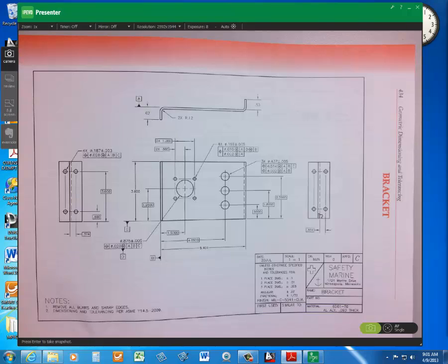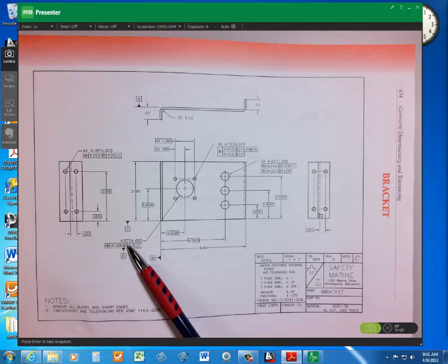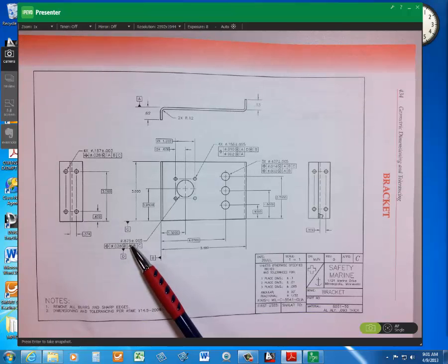All right. Now, the positional tolerances for the actual produced sizes. In reference to this dimension, when we produce it at 0.880, the positional tolerance will be what? And then I'll give you the rest of them. Should be easy to do. Now, it's a max material condition.